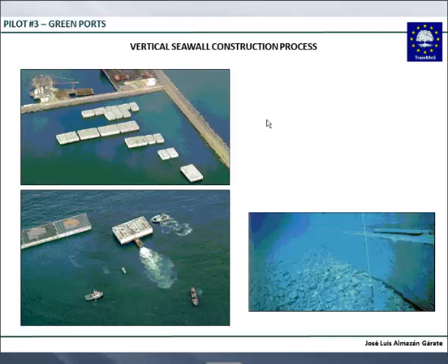If there are things to do above this depth, you do them from the dike itself once it is in position. Very important is how the dike is positioned on the bottom of the sea. The bottom must be flat, because if it is not flat, your caisson will naturally not be horizontal.